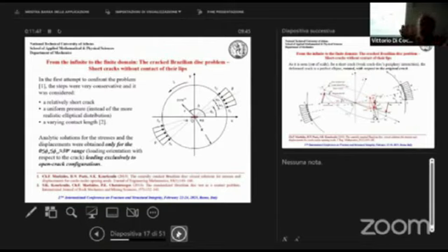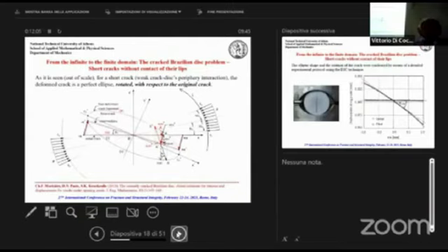We accepted, and this is the case, that while the load increases, the contact arc increases also. It is not, as was suggested by Stavros, that we load the disk at an angle of 1.5 or 2 degrees. This is a varying quantity. So with these assumptions, it was possible to solve the problem assuming that overlapping is avoided, which means that for specific configuration, you can see what happens in practice.